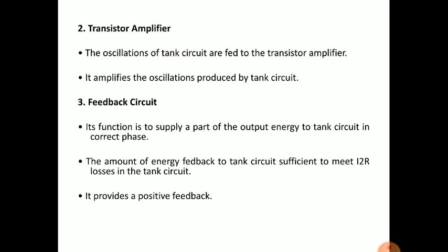tank circuit. The amount of energy fed back to the tank circuit should be sufficient to meet the I square R losses in the tank circuit. Yes, there are some I square R losses because though it is a closed loop circuit, the capacitor and inductor do not produce oscillations infinitely because in practical components there are some losses,